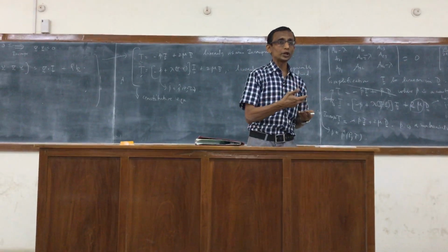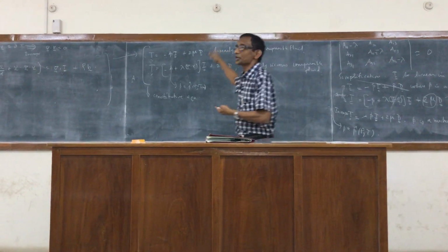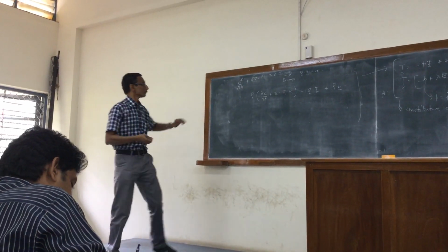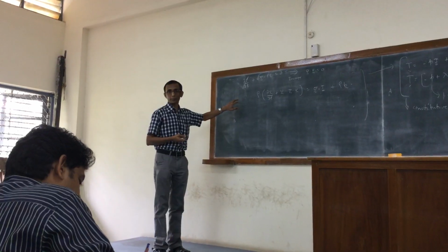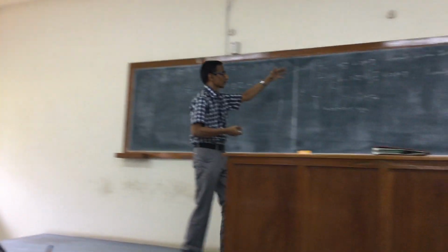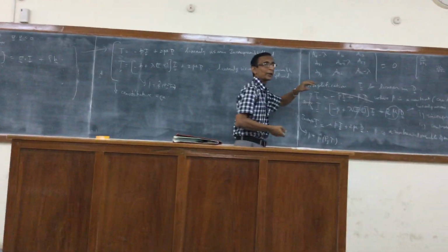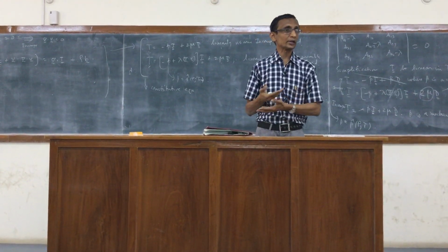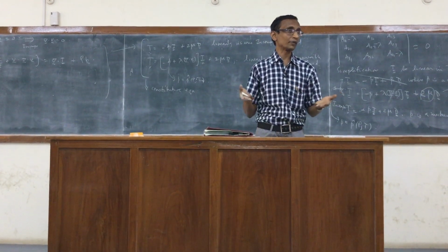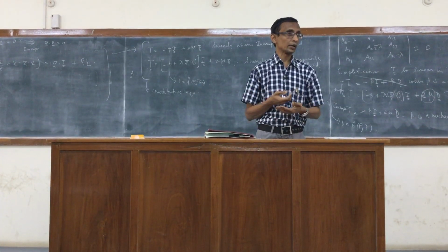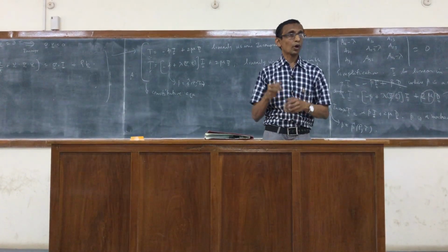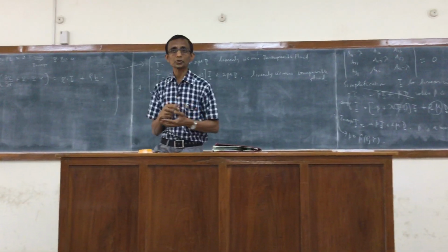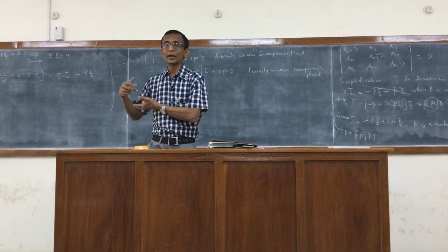Depending on what type of fluid you deal with, you will get different relations between T and D. This is again a limited set of proposals that Stokes came up with, that leads to further specialization to a linear dependence, which is what gives this. So you can see how special the Navier-Stokes equations would be. They certainly cannot deal with what are known as non-Newtonian fluids. Right? But what I also want you to understand is the so-called constitutive equation. The important contribution of Stokes is that there is also a theory behind this.